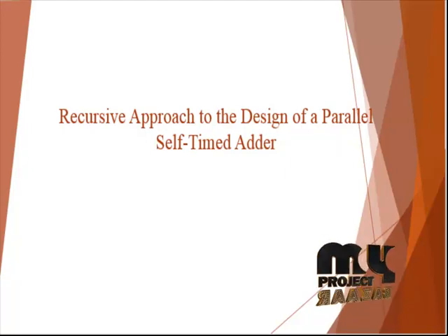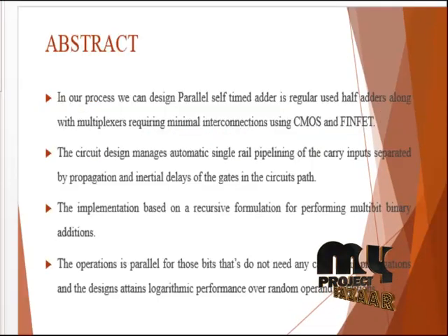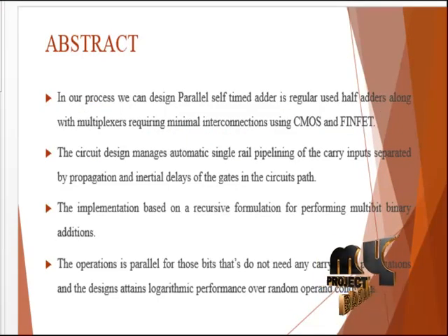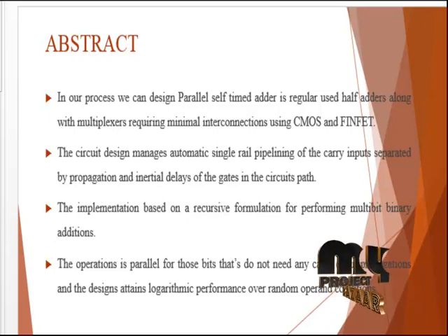Recursive Approach to the Design of Parallel Self-Timed Adders. Now we are going to discuss our product abstract. In our process, mainly we have considered pipelined adders using single-rail data encoding with CMOS devices in the FinFET process. The circuit design is mostly established for the flow of carry signals. In most cases, dual-rail carry conversion is used for the internal bitwise flow of the carry outputs.